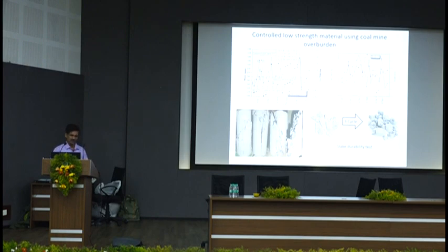We took the cube. The strength was coming around 17 point something. The cube strength is 1.25 times the cylindrical strength, and for the core you get a cylindrical sample. So he said it's coming close to M20 but less than that. And it was not directly retaining the water, it was the roof of the filter house.